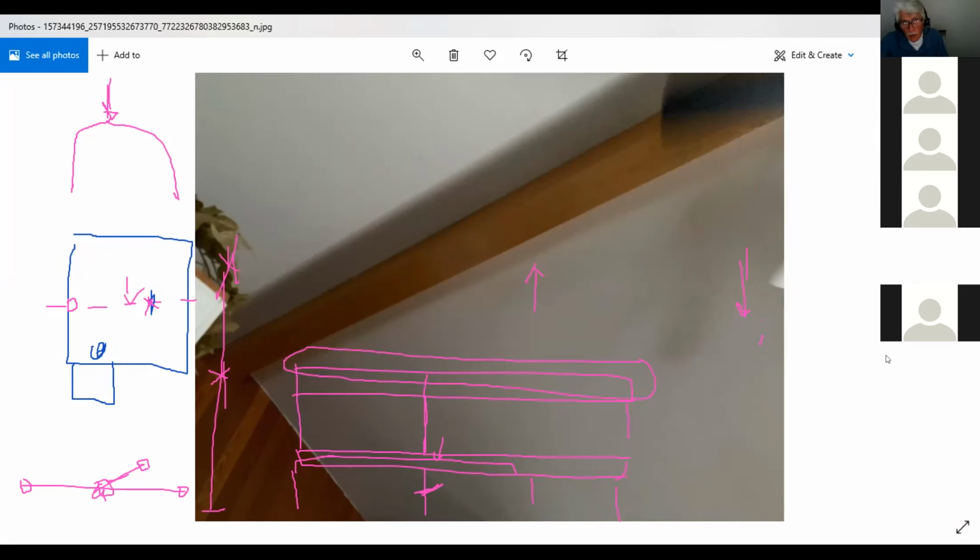And then here they plop two columns, okay? If you're telling me that there's nothing on top of this beam and it's just a floor, well, it's simple. But if that's not the case, if a column comes on top of another column and you want to remove this column and you're analyzing this only for the load of the floor, what's actually happening is all the load of the roof is coming down also on top of that beam.